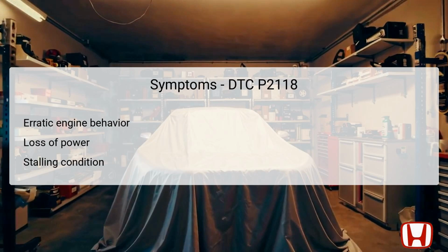The symptoms associated with DTC P2118 can be quite notable. Drivers may experience erratic engine behavior, unexpected acceleration or deceleration, which can create safety concerns. Loss of power, especially during acceleration, is a common symptom.